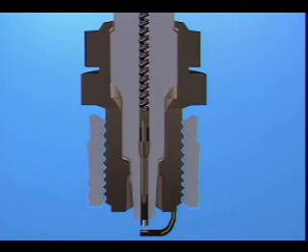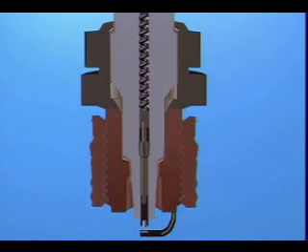Under-torquing also prevents good heat transfer from the plug to the surrounding metal. When the plug is only lightly torqued, the plug is in contact with less of the surrounding metal. This does not provide adequate surface area for the plug to transfer heat to the cylinder head. When the plug is properly torqued, the contact surface area increases, providing for better heat transfer.